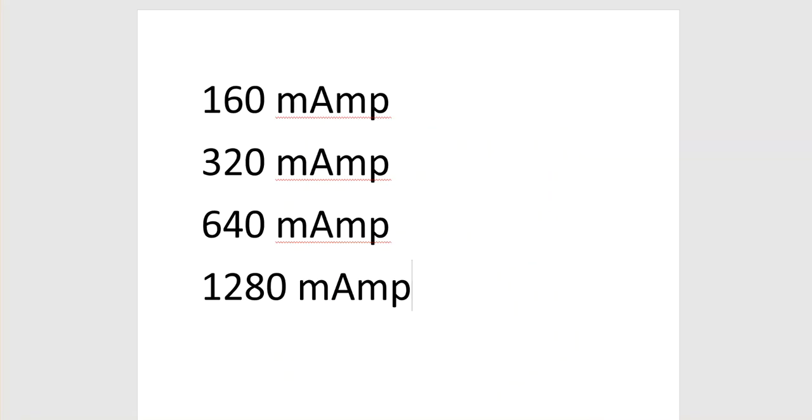Yeah. So, for example, if you want to choose these power supply units, always try to have at least 20 to 30% more power. I mean, when you want to select, if you have 10 devices with each one consuming 10 milliamp, you consider this one.